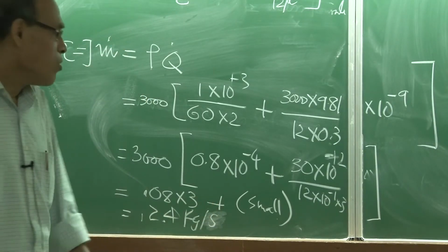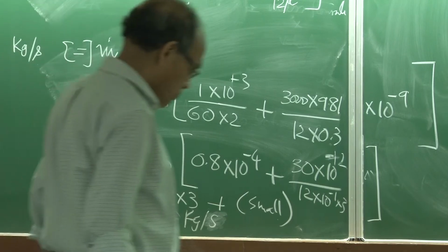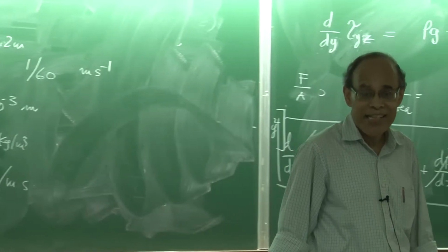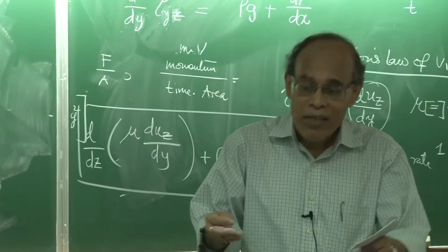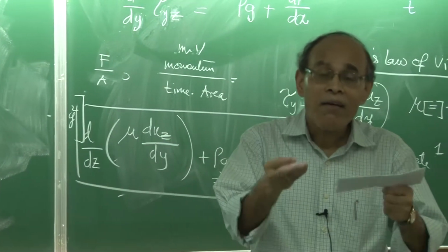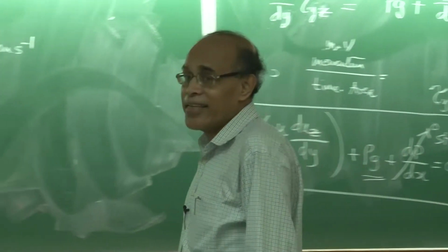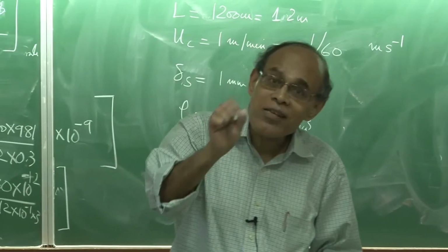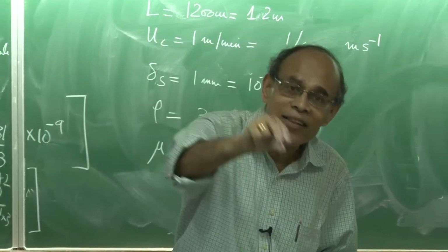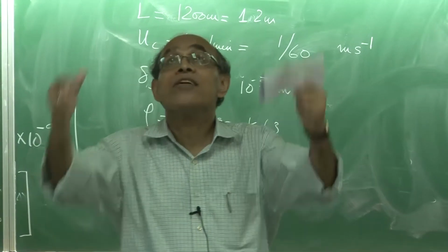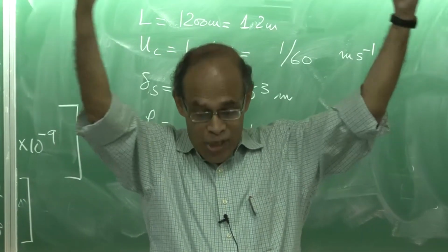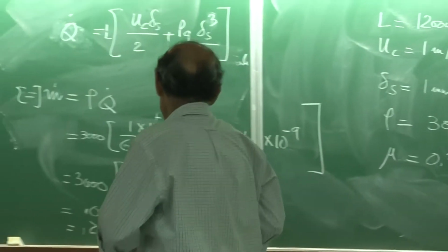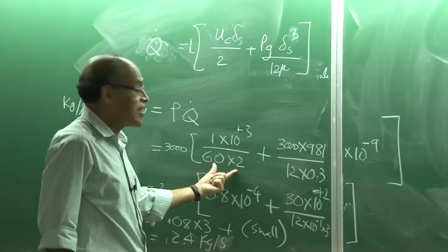So, 0.24 kg, if you multiply it out, is something like 240 grams per second. You can imagine that if an operator is throwing powder over the caster, it has to be done at a very, very small rate. So there are dispensers through which the powder falls at a slow rate. You will be surprised that when everything is so big and moving down, the powder flow rate is not large, and most of the powder flow rate under the given condition is dictated by the casting speed.